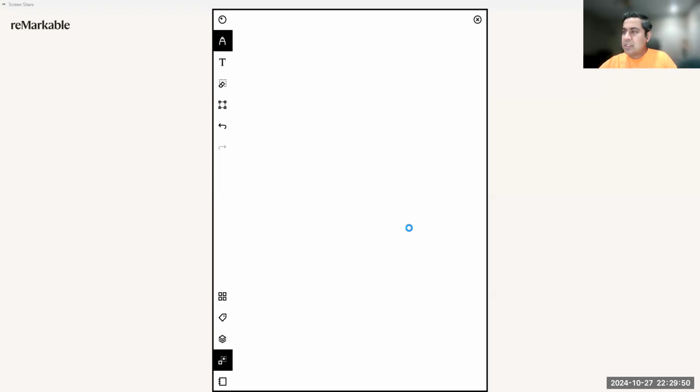If we are creating the reverse active region operation, then we connect a source at the collector in this direction, so that the collector base junction will be forward biased, and then we reverse bias the base emitter junction.